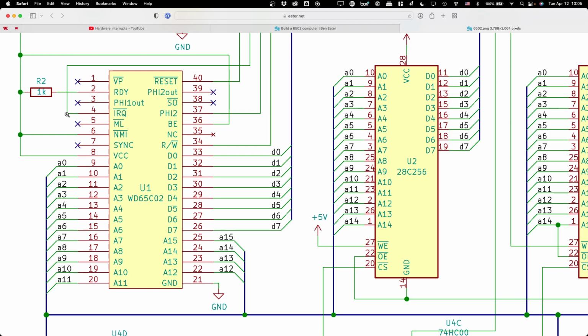The reason is that when you hit the button, the processor is interrupting, updating the counter, interrupting, updating the counter, interrupting, updating the counter. So the longer you hold it down, the more interrupts are happening.